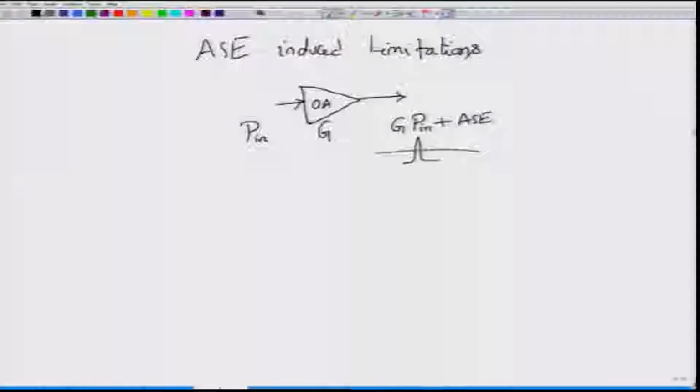Therefore, if you want to work with the optical output that is coming out of the amplifier, you somehow have to also limit the amount of noise that is entering the subsequent components of the optical link. You do that by putting an output optical band pass filter, in order to limit this amplified spontaneous emission noise only to the bandwidth that the signal occupies. So, all the components of the amplified spontaneous emission noise outside the bandwidth are equal to 0.